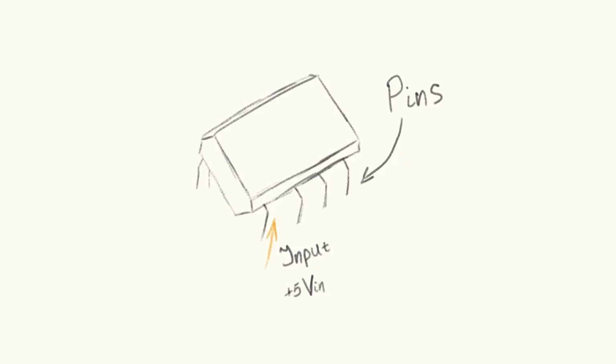If, for example, it's input, it will quote-unquote listen to the signal that will come on this pin. And it's just voltage. Digital means either high voltage or low voltage will be on that pin, and it just constantly listens to this high or low voltage level. If we configure this pin to be output, that means we will output either a high level of voltage or a low level of voltage.